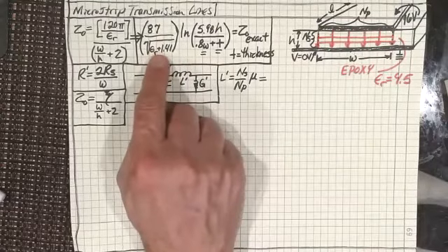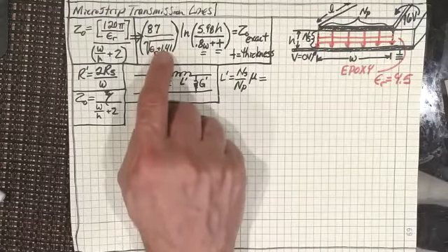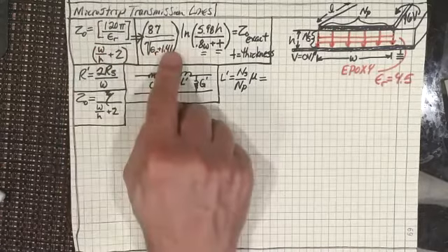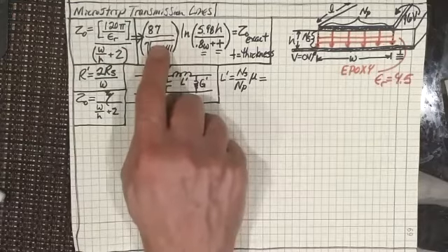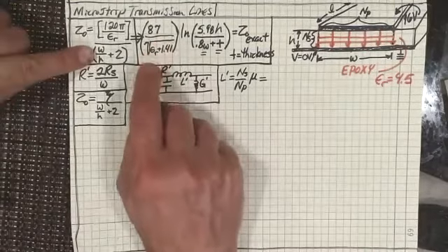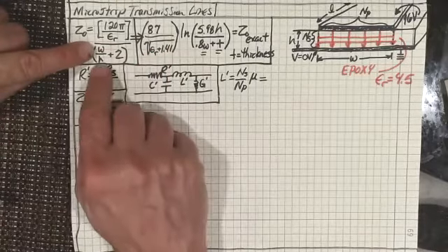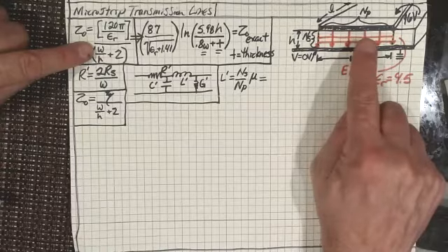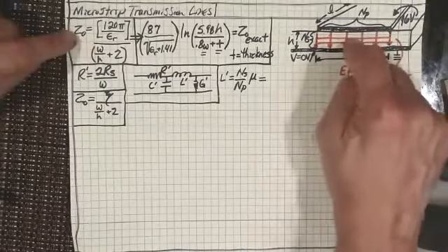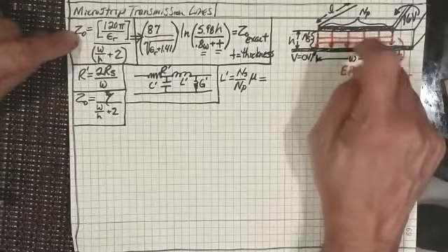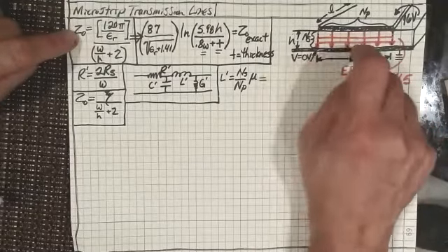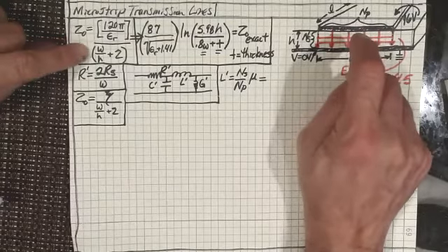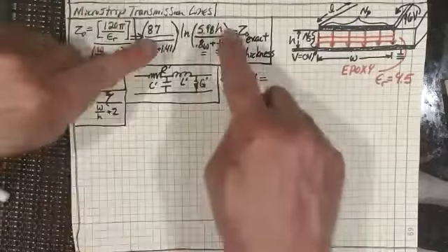And when you go out and start working as an engineer, are you going to be working with this theoretical equation, or are you going to be working with this equation when you start to figure out what the ratio of width to height of this microstrip transmission line is when you want impedance matching? So you want the impedance of this, which is, let's say, 50 ohm, to match up with the next thing you're connecting it to, which also has to be 50 ohm. Are you going to be using this equation, or are you going to be using this equation?